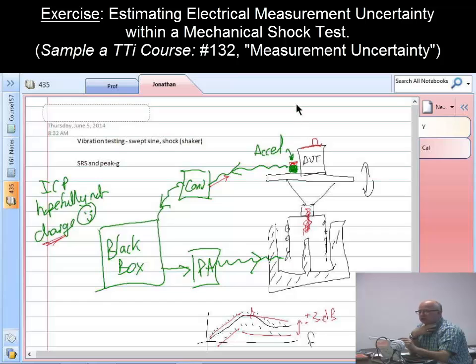If you're using charge accelerometers, this conditioning now happens inside the red box here. There's this box here, and on this cable, at this stage, there is no voltage or current sent down. It is now carrying a charge, and this becomes very, very sensitive to noise pickup, electronic noise pickup. That's why ICP accelerometers are preferred these days: it's the same conditioning, but whether it happens at the accelerometer end or at the other end of the cable, it reduces the electronic noise pickup.